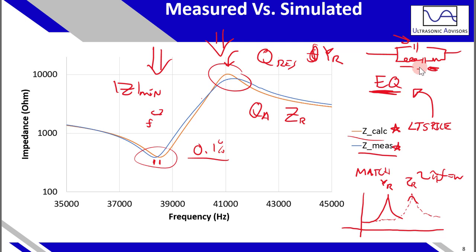So just note that there are going to be discrepancies, and those discrepancies can be insightful, but for devices where you're mainly concerned about resonant frequency, you would opt toward using parameters measured there versus resonance and anti-resonance. But plotting your measured data and calculated values on top of each other, if you have a need for accuracy where you're operating your device, that's the best approach.